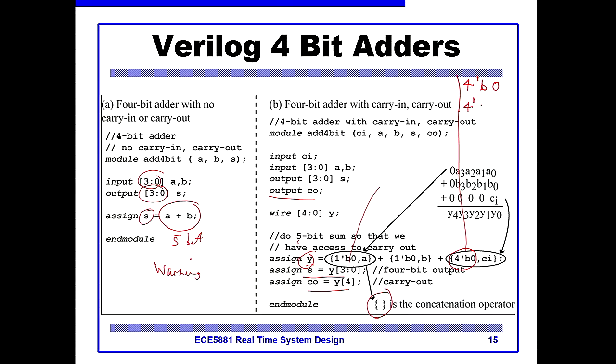We could have written this as 4'd0 for decimal, and you can use octal as well, and hexadecimal and other radix values. But the convention is when you're dealing with bit level, you stick to binary or hexadecimal, because it translates directly into the format. The advice is you should use decimal when you have large numbers and you don't want to do the conversion into binary manually because you'll make a mistake. So you use decimal wherever possible, but binary for bit level manipulations.